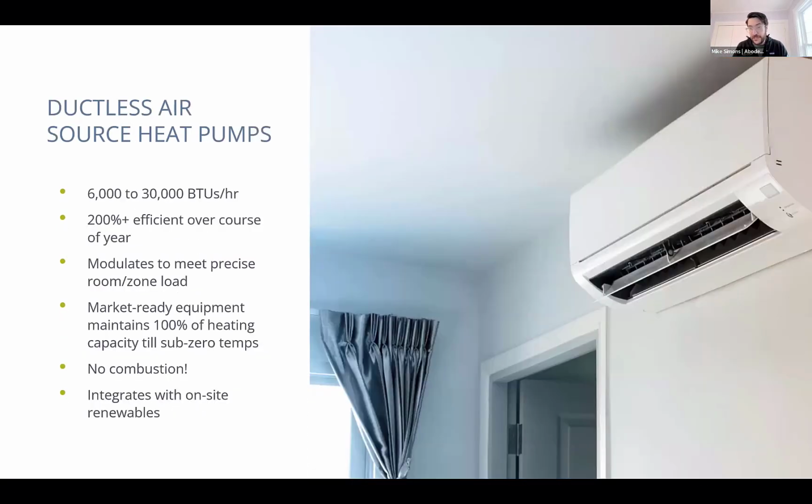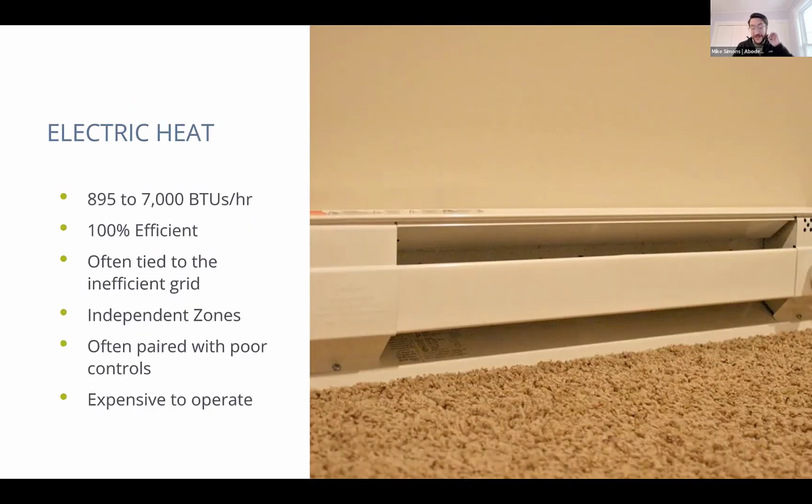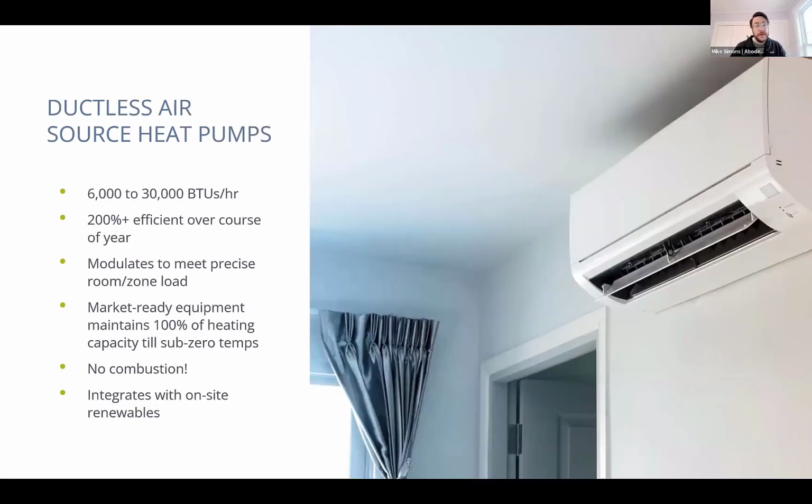But unless you live in an MLP town with very good rates, electric heat is oftentimes extremely expensive compared to all the other options, because as you are buying a kilowatt hour, you are buying all of the inefficiencies of the power plant, all of the inefficiencies with today's grid, and you're not getting that magical COP or multiplier that you would with a heat pump system.